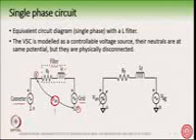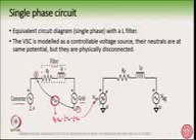Okay, so this VAN is nothing but 2/3 VAO minus 1/3 VBO minus 1/3 VCO. So this is the VAN, which when we put it into a circuit, we treat it like this. Okay, we put this one here. So from this circuit, this is the actual circuit. On the left is the actual circuit and on the right is the equivalent single phase circuit.